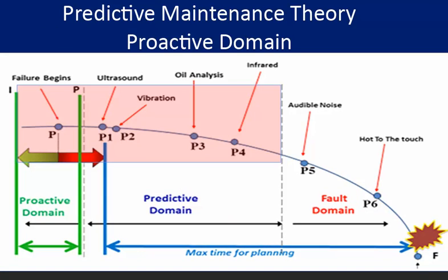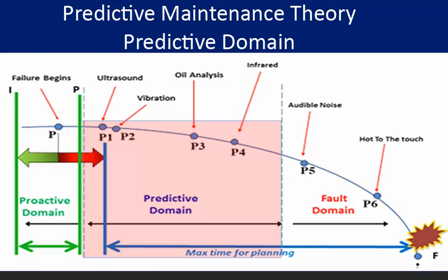Ideally, an initial PDM survey would be planned directly after installation to check for installation faults as a part of acceptance testing and to establish operational baselines to be used as comparisons for later PDM surveys. Early signs of failure can be detected months before a catastrophic breakdown by using PDM techniques. This allows time for planning production downtime, ordering replacement parts, and planning for manpower being off shift.